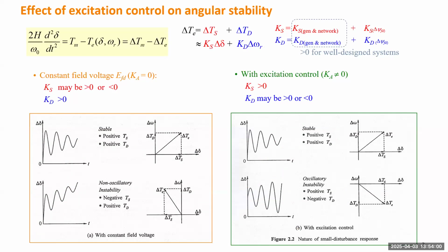I stopped here for a second because those waveforms are very useful. If you simulate a very large system and there's some disturbance, you see many generators become stable, and there are a few generators that become unstable. If you see any generator behave like this one, what does that mean? That generator has very weak excitation control. If you want to make that generator more stable, you need to try increasing the gain. If you are allowed to adjust the model, that will definitely be better and will bring this generator more stable.